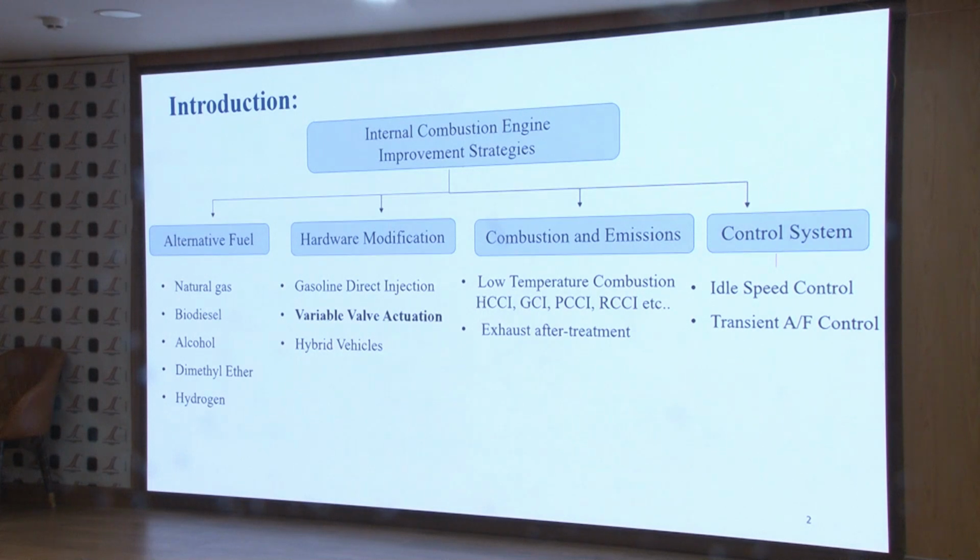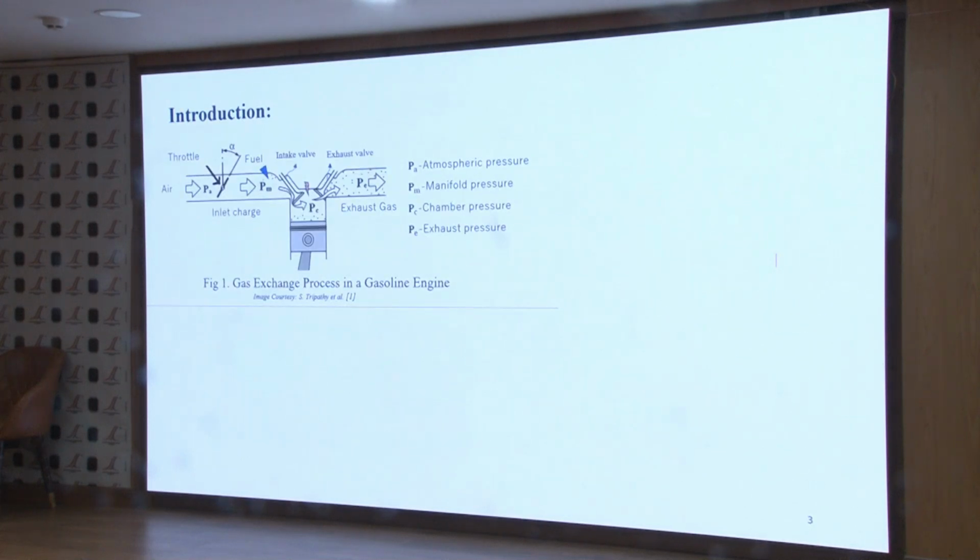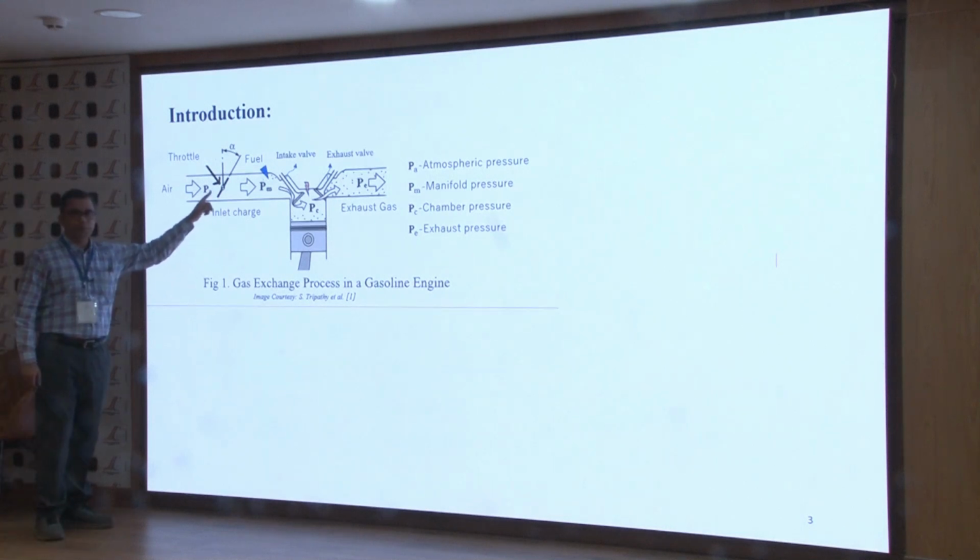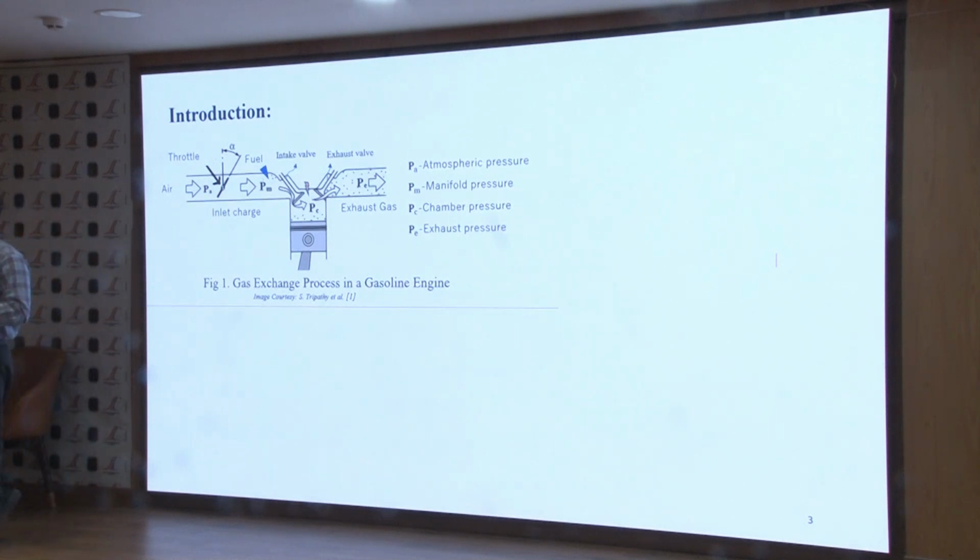If you look very carefully at the engine, we need to think. In the SI engine, we have a throttle. The main function of the throttle is to control the airflow rate. But at this present moment, do we need to think about whether the throttle of the SI engine is really necessary? Why have we not come out of this throttle part till now?